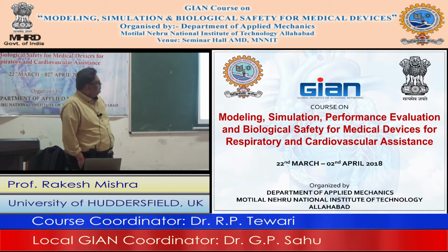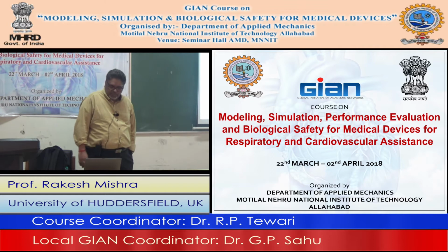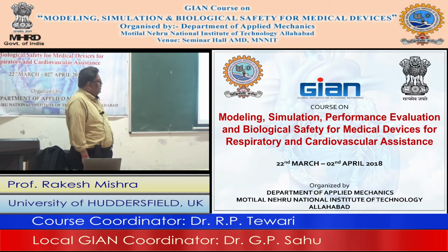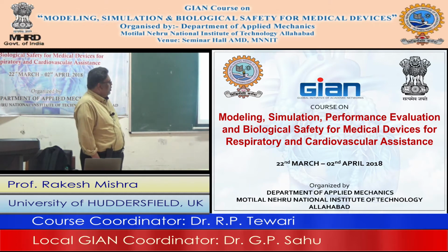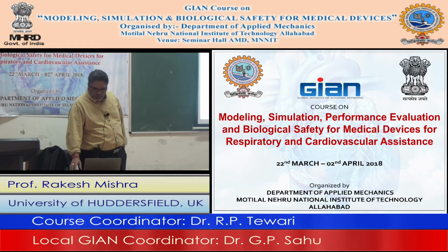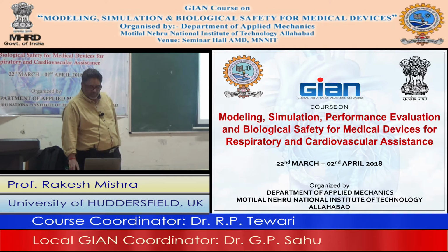analyzed the performance of an axial flow ventricular assist device, which is allowing 0.08 kilograms per second of blood to flow at 9500 revolutions per minute. And what we are doing is, we now have to consider a systematic investigation to obtain the flow features within the VAD, and we would like to obtain the performance curve for the ventricular assist device.